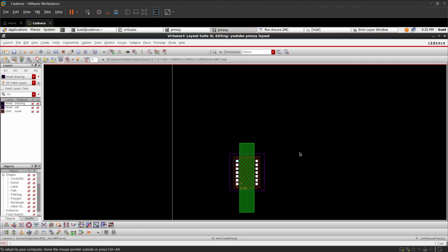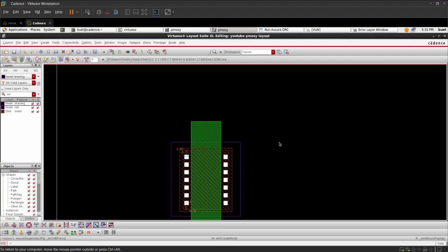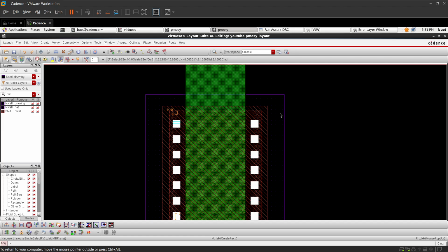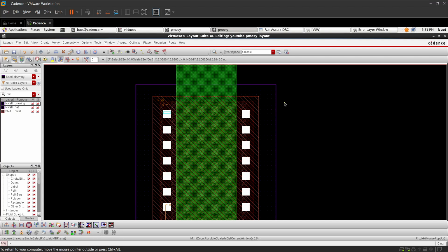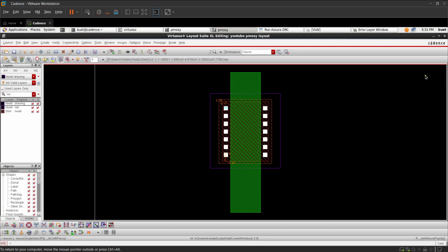Okay, because whatever the black screen you have been seeing, that is a P substrate. Into the P substrate, we have our body terminal should be of N type, right? So the NWell will isolate your overall PMOS design from your P substrate. For that, the NWell is going to be formed. Whenever fabrication goes on, there is to be a P substrate, and in that NWell formation is to be done. In that NWell, we are supposed to do our PMOS. For NMOS, we are going to do directly on P substrate only.